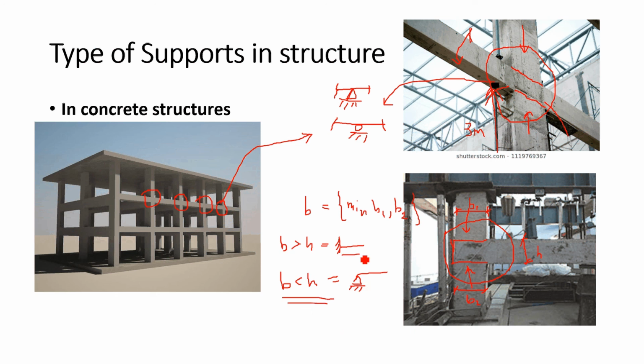You will get this particularly in precast concrete members, because in most cases you will get the slab here, since slab and beam are constructed at the same time. So what we consider is the depth of the beam here, including the slab. Here in this case, this is the depth of the slab and beam. Therefore most of the cases you will get this second one.